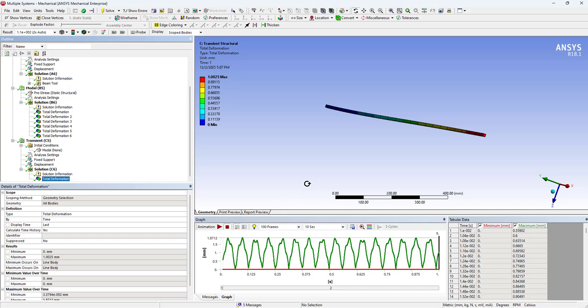So in this case, we switch to the case where ANSYS is using explicit method for solving the equations, and it will take quite less time for solutions as compared to the implicit method. So implicit method is good for a very small number of points where we are finding the details at low velocities or finding the response like this.